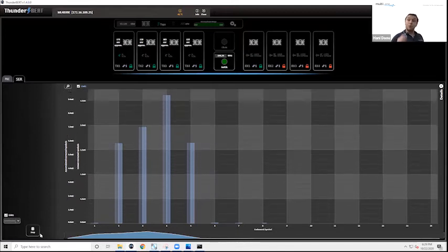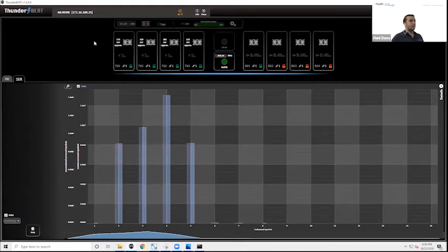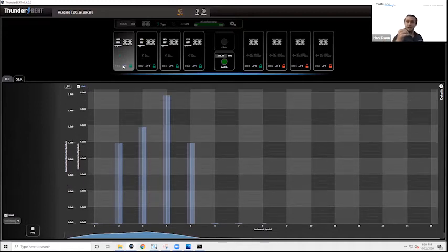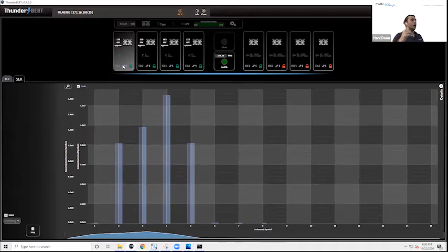Our symbol error rate histogram, which is what I'm showing right here, is a depiction of every single code word, how many symbol errors it is getting. With KP4 FEC, remember, the highest number of symbol errors that you can correct per code word is 15. So even with the aggressive error counts, even with lowering the magnitude of the tap equalization that we have implemented here, we are still operating with a bunch of margin.